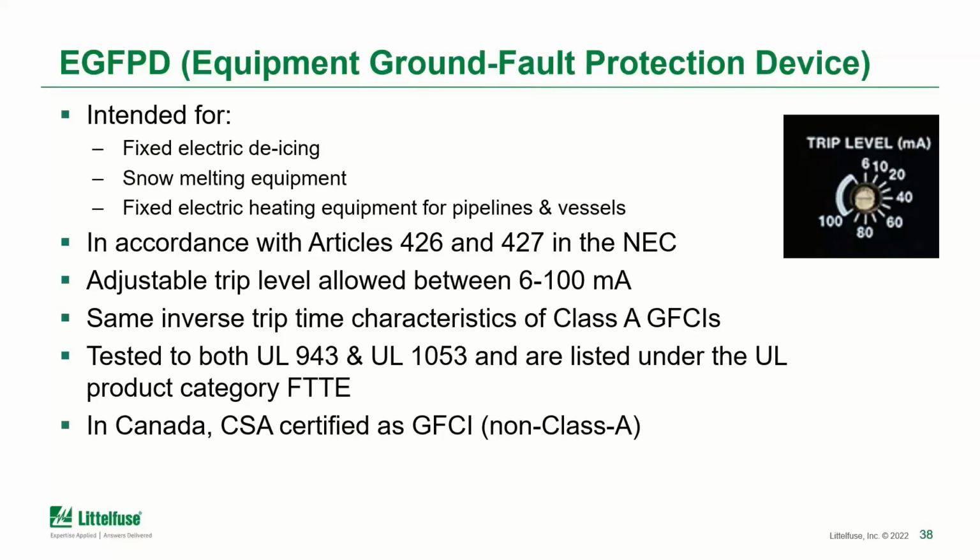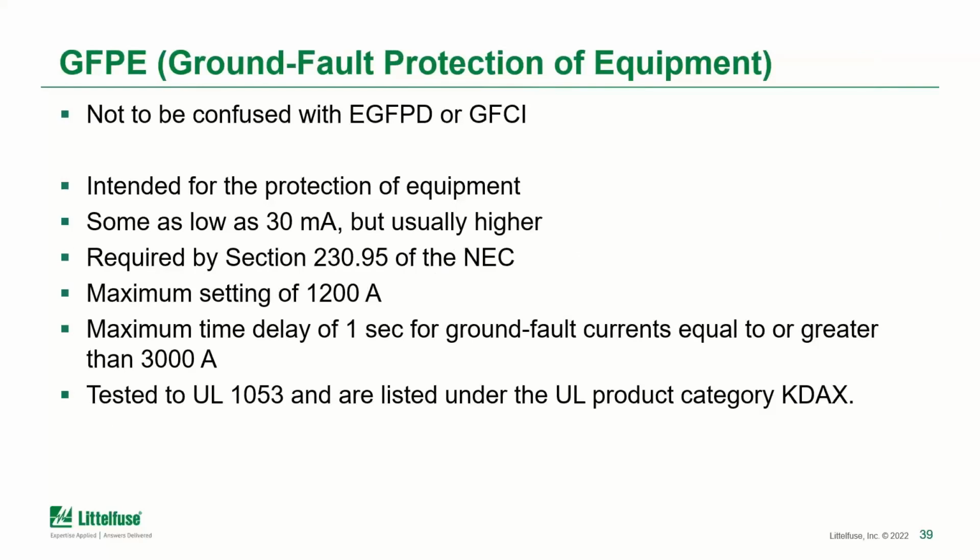Except in Canada, because the standard is a little more open with the wording, it actually can be certified as a GFCI. It doesn't meet the Class A, but it can be certified as a generic GFCI. Now, I may also talk about GFPE, or ground fault protection of equipment. And so this would be the standard ground fault devices that you might have in an industrial circuit.